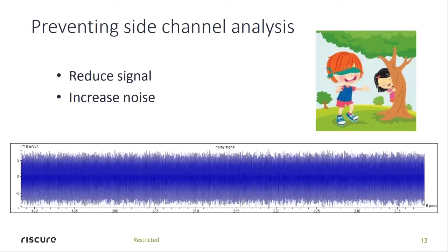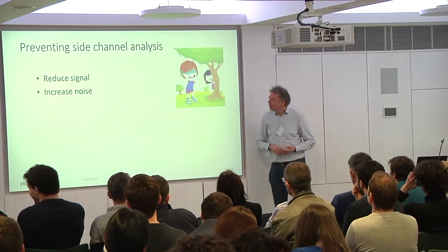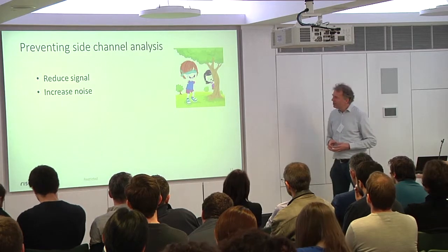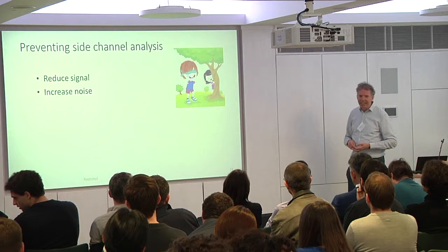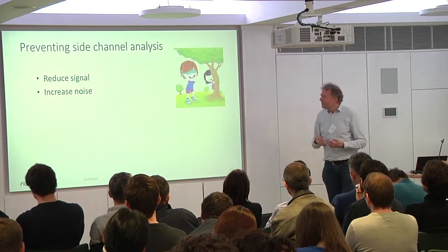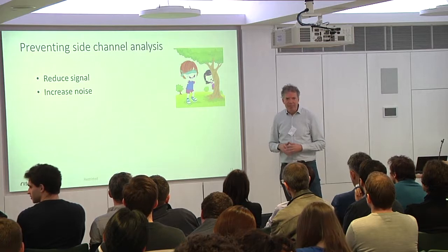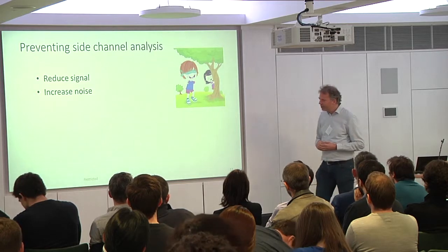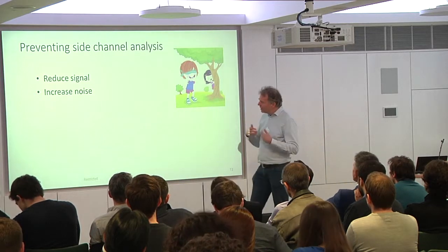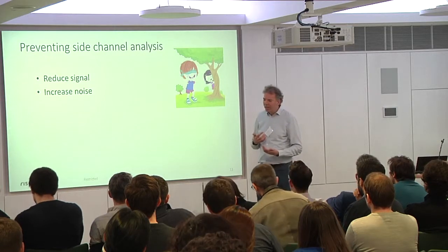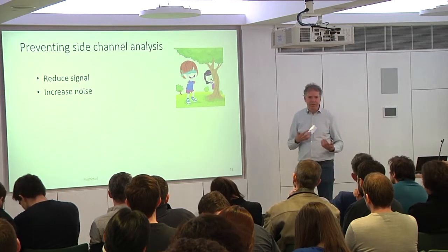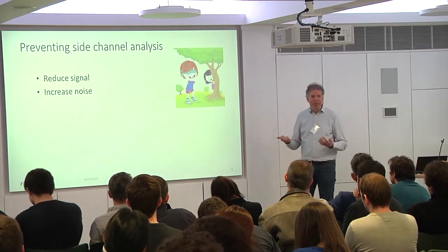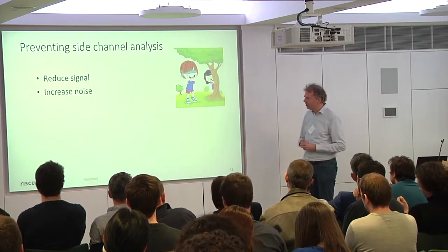So things are changing now. So vendors are trying to reduce the signal and they're increasing noise. So it's becoming a hide and seek game. Yesterday when Francisco did his presentation, he talked about WDDL, he talked about masking. These are methods to reduce the signal. Typically the signal is not completely gone, but it's just getting less. Increasing noise is something that would happen when you deliberately start a process that makes a lot of transistor switching in a chip without having any specific activity related to that.